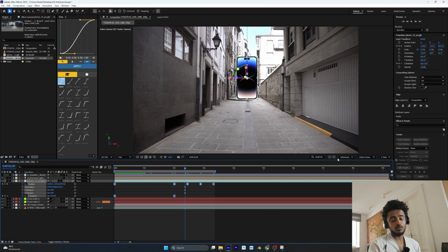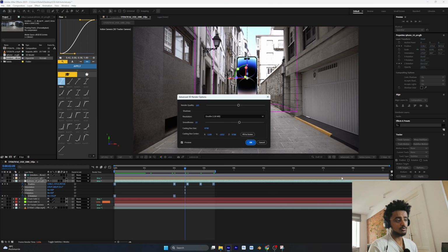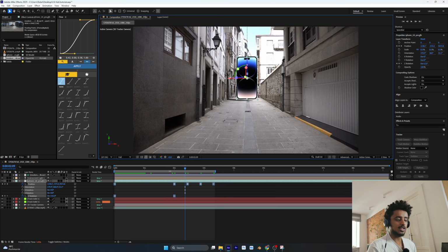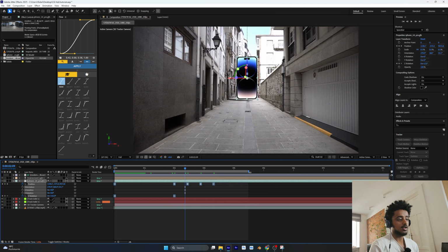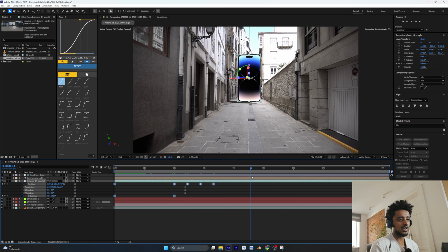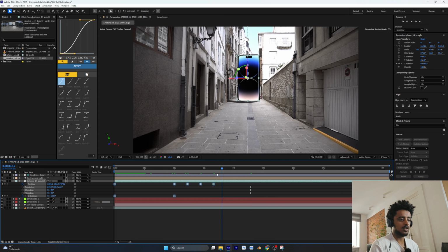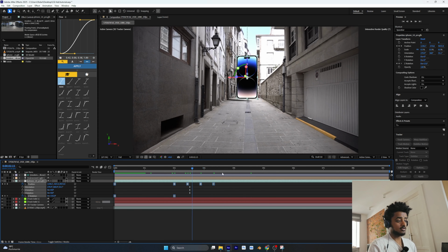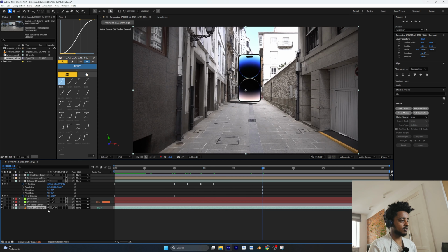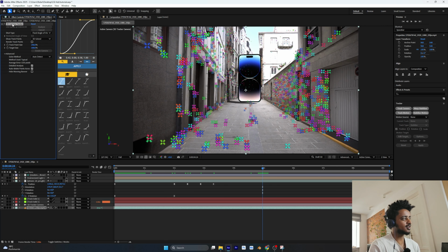And if you want the shadows to be more realistic and advanced, as I told you, you can go to render options and you can pump up this render quality and smoothness to the max. And then you can have a better one. And now I'm going to show you how to add the 3D assets on the wall and on the ground. It's basically really easy because we already packed the camera, so we have most of the things we want.